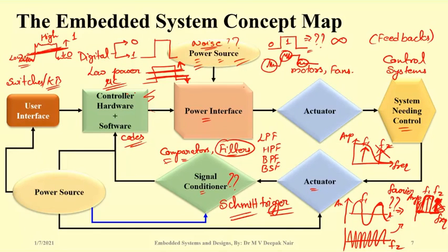So this is a more precise or more accurate design compared to a comparator. Keep these things in mind, that a Schmitt trigger provides you two threshold values, whereas a comparator only provides you one threshold value.